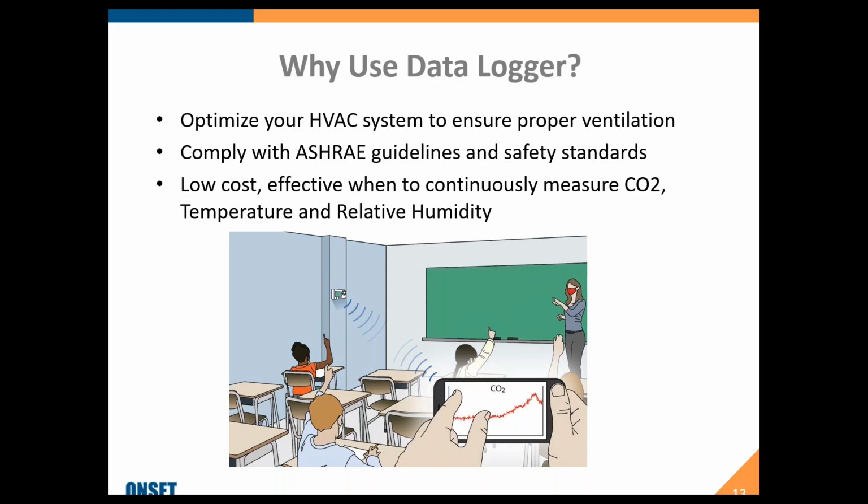You want to be able to comply with those ASHRAE guidelines and safety standards that Scott was talking about, that 800 to 1,000 ppm or the 40 to 60% relative humidity. Another reason to use data loggers is because they're low cost, accurate, effective ways to measure those parameters, especially those three parameters: CO2, temperature, and relative humidity.